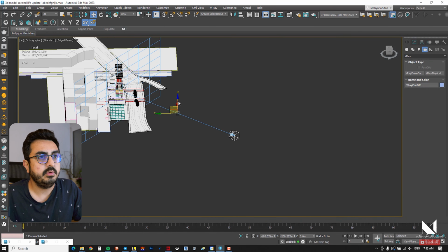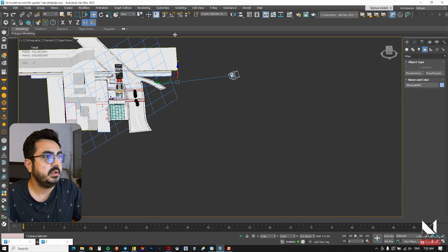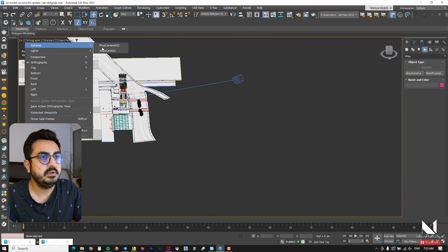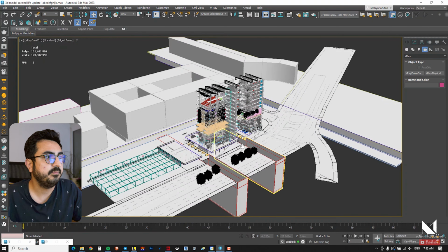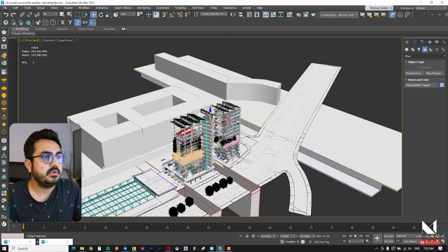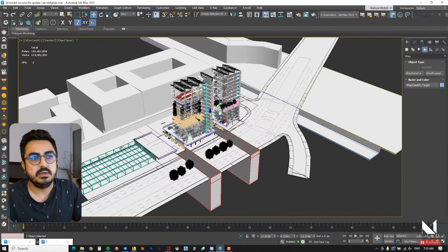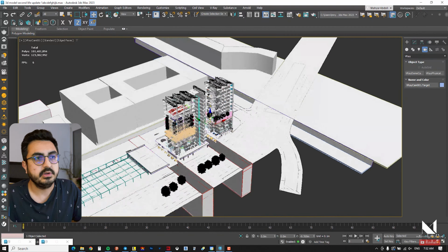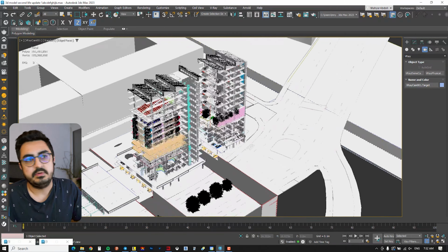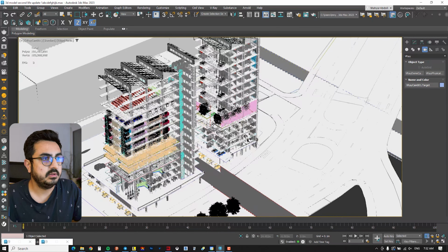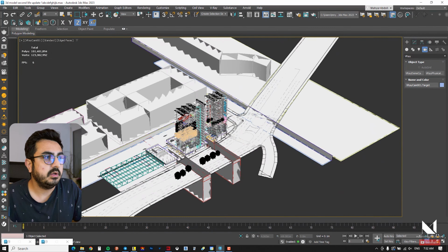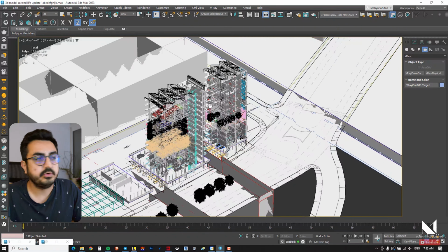An important point to remember for V-Ray cameras is that you cannot have a technically strict orthogonal view to capture a flat view of the scene. It will always be in perspective. You cannot make a V-Ray camera truly orthogonal. However, a trick here is to set the camera with a telephoto lens. So pull the camera further back and increase the focal length to a higher number.